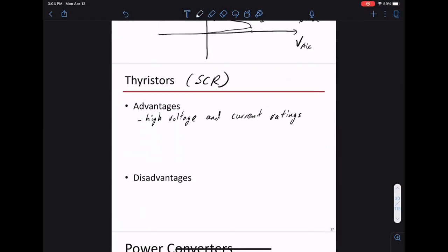So it's more robust than a switch, because a switch is definitely more limited. Switches are designed to operate at tens, even for power transistors, tens or hundreds of kilohertz, whereas this thing operates once an AC cycle. So it's more limited, but you can make it much more robust. This is really cheap as well. It's cheaper than a power transistor.